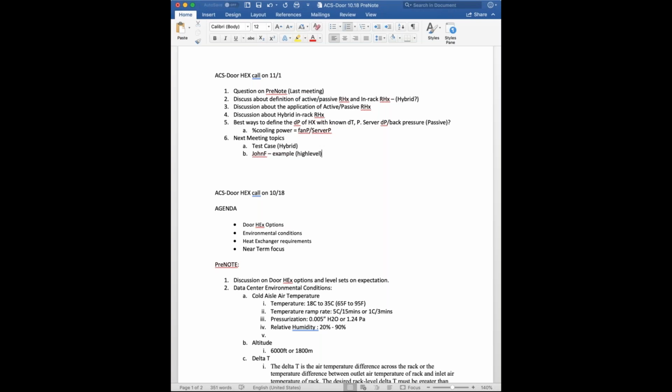Well, is there any kind of ratio, say if the pressure drop of the rear door heat exchanger is about 5 times greater than, I don't know, maybe I'm just making up a number, 5 times greater than the pressure drop of the system, the server fans, then maybe it's better to go with the active fan. It will be much lower than that. If you look at the server, the room for airflow through the server is minimal. If you look at the room for airflow through a back door coil, it's large. So the pressure drop that the IT fan has to cope with for the server itself would be significantly more than the cooling door. Because if you look at the square feet where air can flow, it's the whole door. If you look at the server, the air has to go through all the systems, around all the corners, around everything. There's almost no room for air in the server.